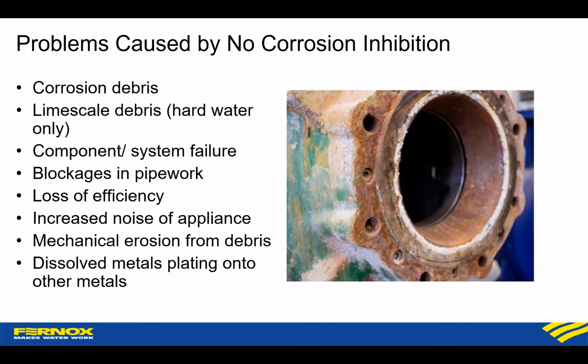But we've had it before where you only need a bit of dissolved copper, say, to then crash out of solution onto another metal, and then you have two dissimilar metals electrically bound, effectively plating the other metal. And it's then where you start getting pitting problems. And you can get problems even in something which is normally fairly resistant to problems like stainless steel.